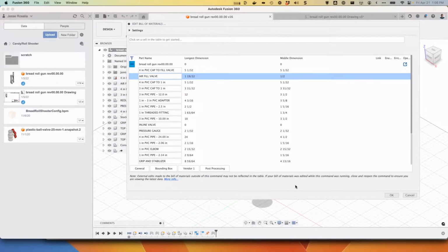But imagine you were using BOMMER for, let's say, building a cabinet or building a table or some other piece of furniture. You might need to know board feet that you need to order. You might need to know what my thickness of my sheet metal would be. And all of that information is available via these BOMMER properties that we pull out of Fusion 360. This data is exactly the same data that you would get by going into the individual Fusion 360 properties. The biggest difference, as you can see, is it's the entire assembly. So if I need to get my entire assembly data out, this is the fastest and easiest way to do so.